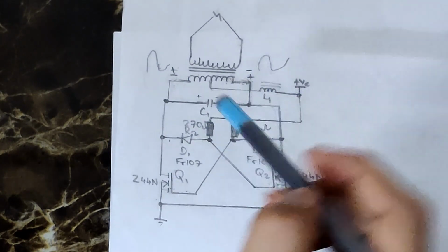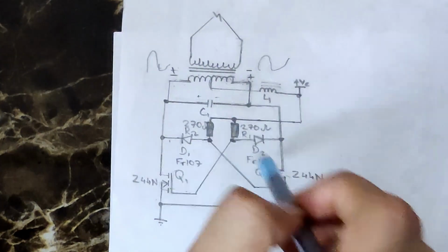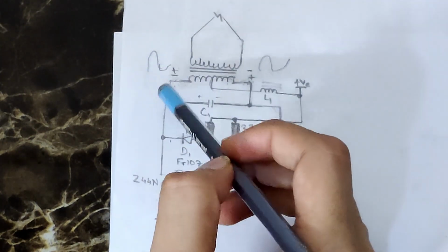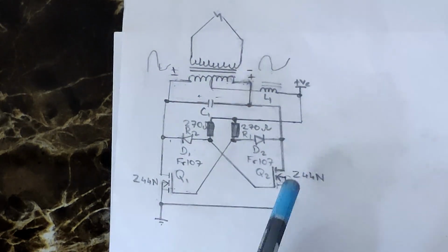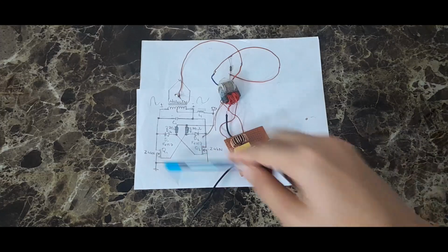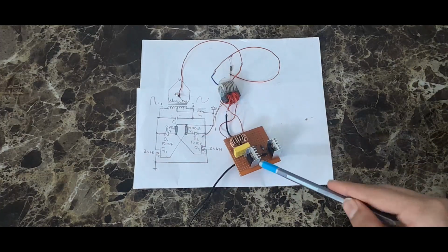On the way down, this diode will conduct, turning Q1 off. Q2 will turn on and this point will go low, this point will go high. The voltage will swing up and down. On the way down, this diode will conduct, turning Q2 off. And the cycle repeats. Now we know the working of the circuit, and here's the circuit that I built on